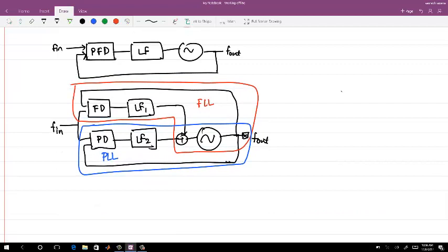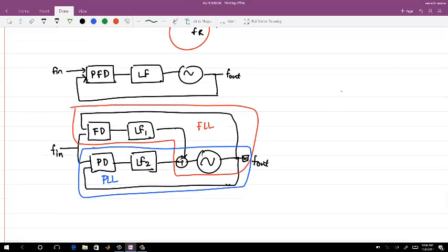Means I have never designed it that way, but I think if you use CML logic, current mode logic, with sinusoidal signals as the input, then your PFD input to output characteristics will also turn out similar to what it is for CMOS logic levels.